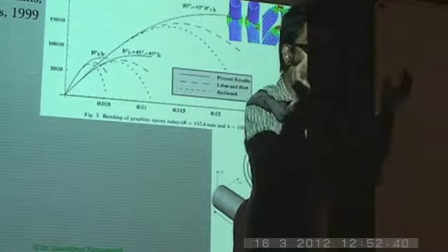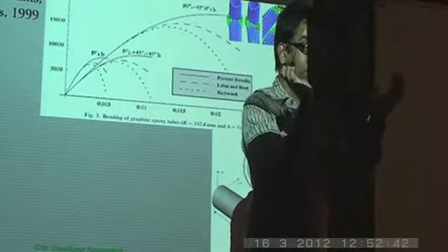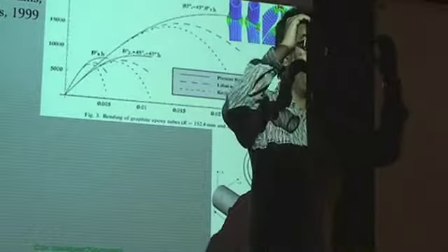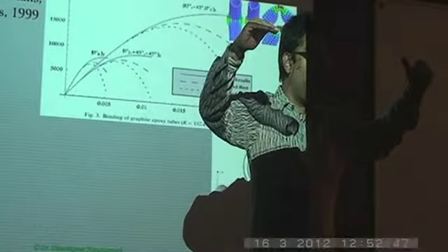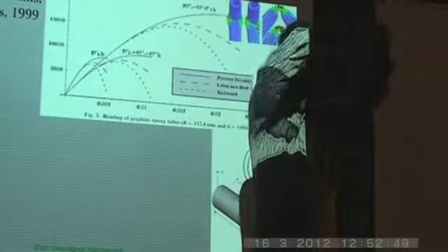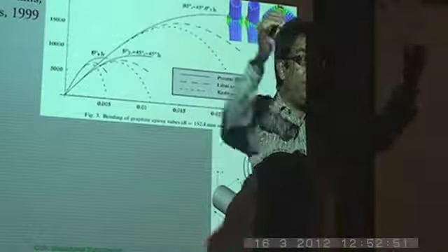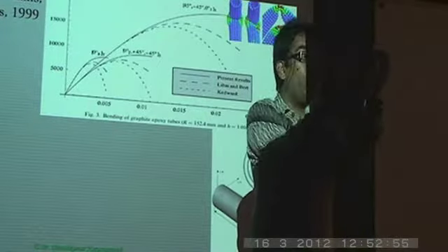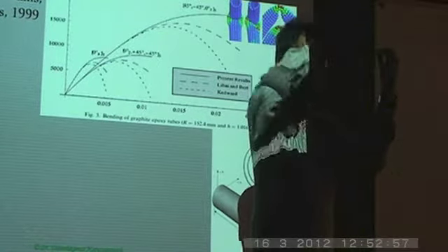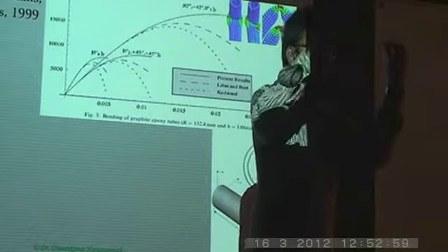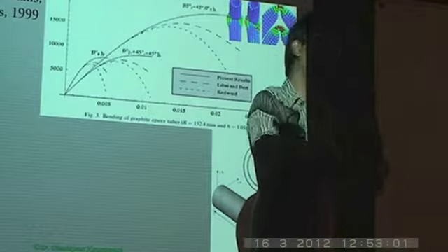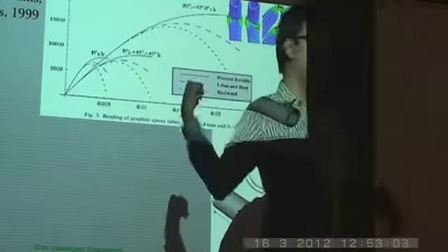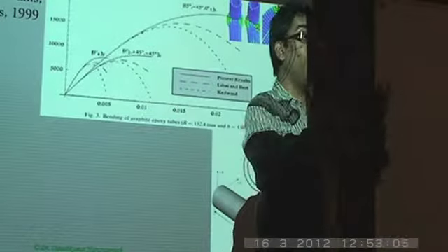Remember that bending is resisted by tension and compression. So if I'm applying a pure bending like this, the top surface is under compression, right? So the top material elements will all be under compression. So there can be phenomena of local buckling also taking place. There will be kinks which will be formed over there. So that can also occur sometimes before. That is not this limit moment instability. These are two different things.